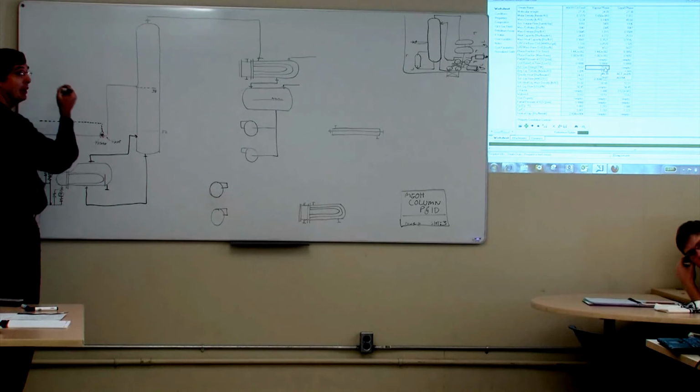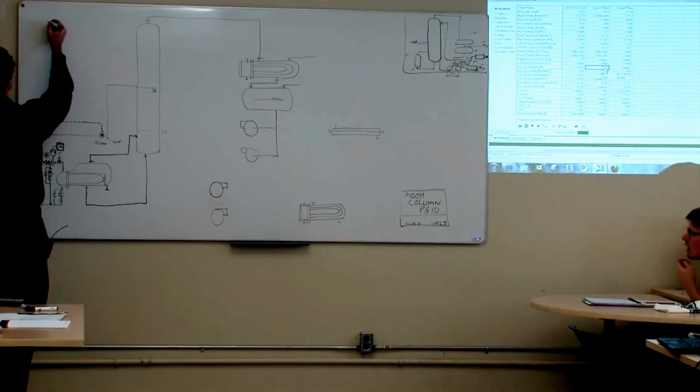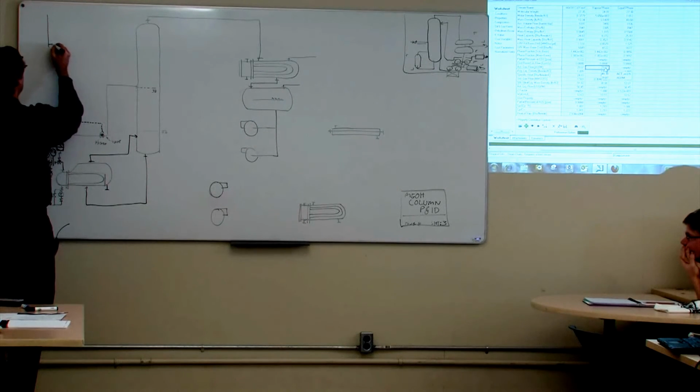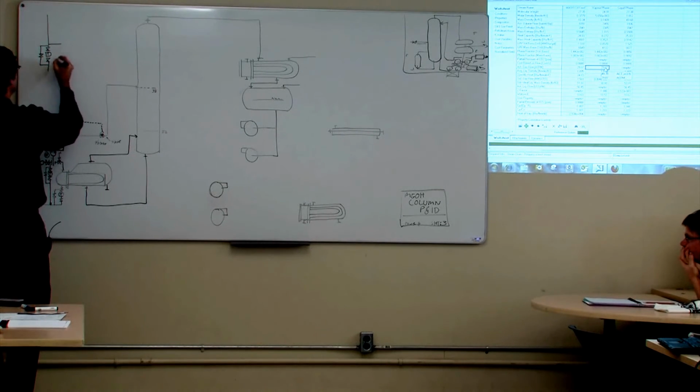Well, the way the piping would actually have to be done is this. You usually would have to come down from the pipe bridge, and then they'll have an elbow or a T, and they'll put the steam trap in like this, and a bypass around it like that. I should show you a picture of this. I have it somewhere.